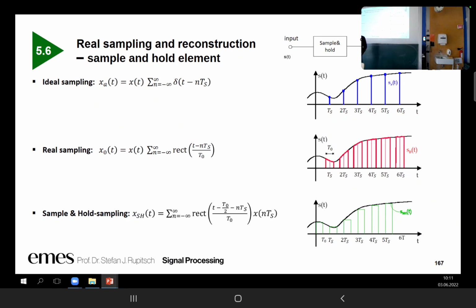For the reconstruction, it's another reason. But if you think about the sampling, a hold time is always good for the subsequent electronic components. Physically, because you have to charge capacitors, discharge, unload, reload capacitors. And for this reloading, unloading, recharging, you need time. And you can use this hold period, this hold time, to do this.